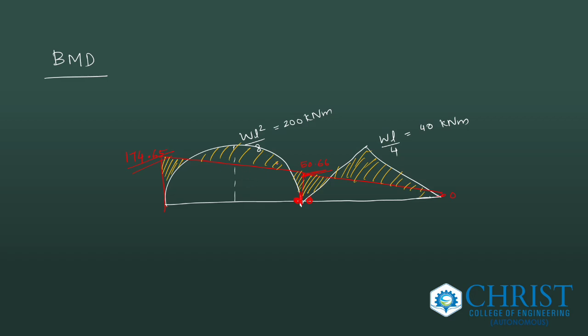And then we are superimposing the simply supported beam condition. That means what happens in a real structure is that we are converting the bending moment of a simply supported beam to a fixed end condition. So there is a redistribution of moments at the support. That's what happens. That's why the bending moment diagram of a simply supported beam is converted to something else, or it is opposed by the fixed end moments, and the resultant bending moment diagram will be the actual bending moment diagram of the structure.